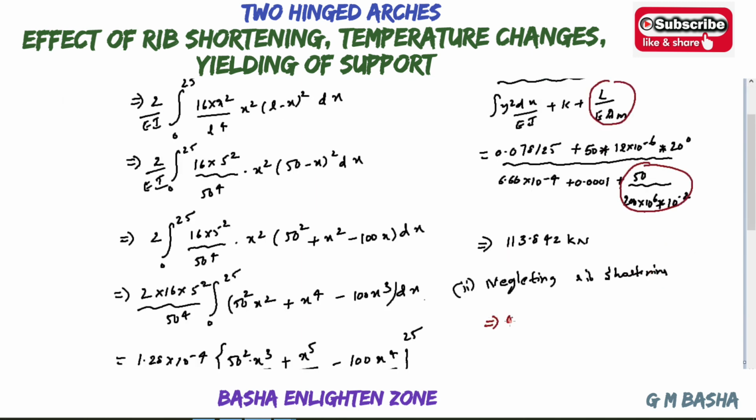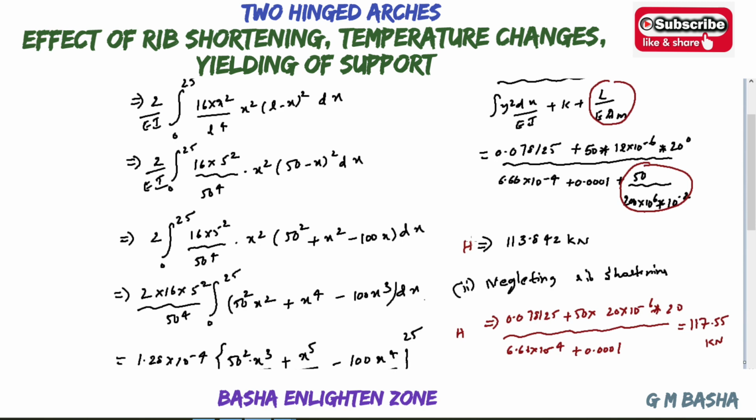So let us simplify once: 0.078125 plus 50 into 12 into 10 to the power of minus 6 into 20 degrees centigrade, by 6.66 into 10 to the power of minus 4 plus 0.0001. Don't take this value in, because we are neglecting the rib shortening. So the final value will be around 117.554 kilonewton. This is the horizontal thrust developed when neglecting the rib shortening, and the earlier one is the horizontal thrust developed when considering the rib shortening. So this is the way to solve the problem.